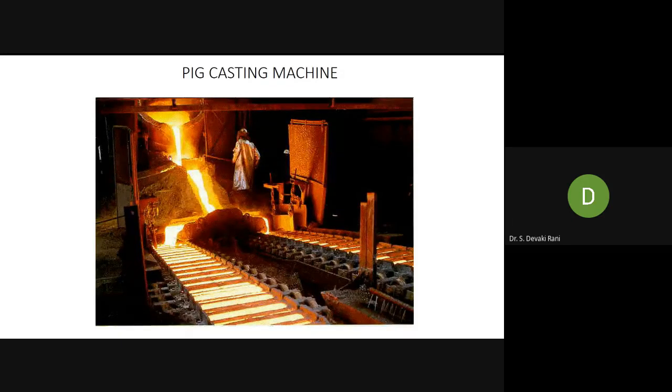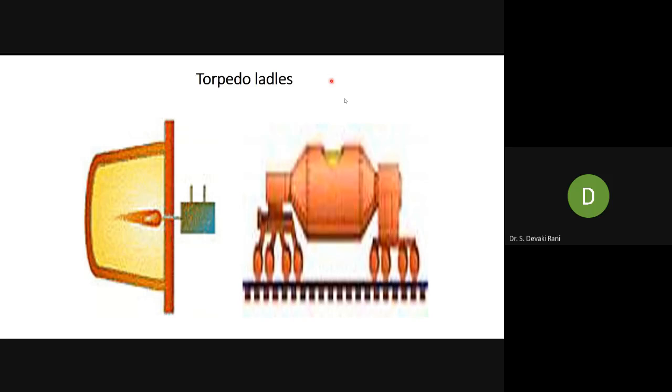It is slightly tilted, so the hot metal is falling into these pig casting machines. These pig casting machines are rectangular in cross section. When the hot metal comes into the pig casting machine, the machine moves on rollers up to here. By the time this roller comes here, solidification is over. So the pigs are removed, and they can remelt them and charge them into the blast furnace.